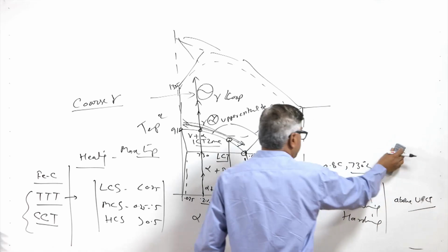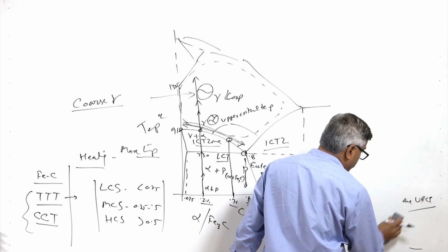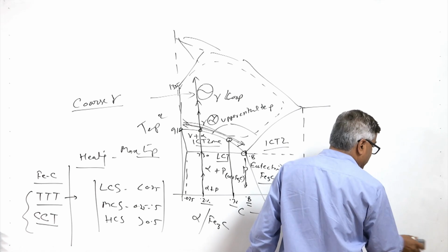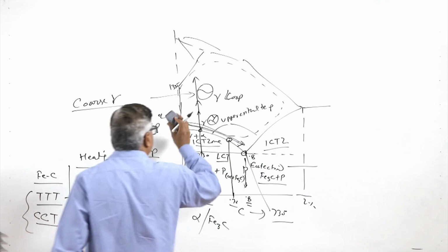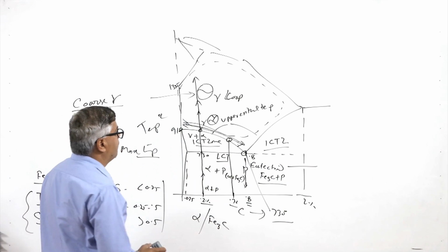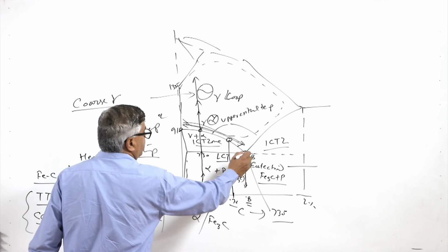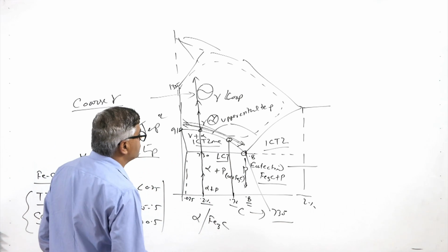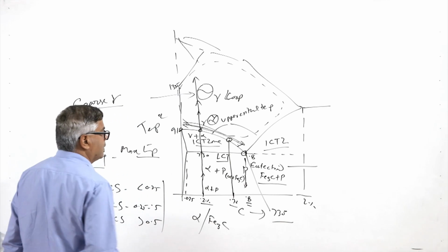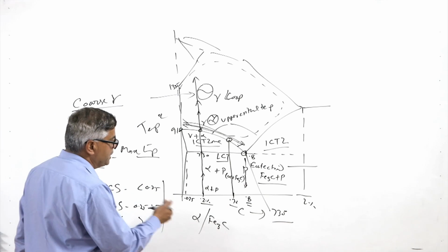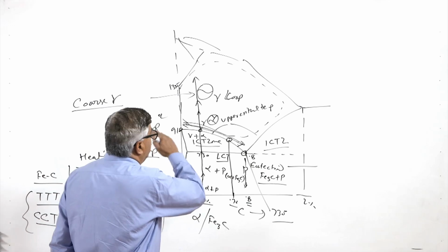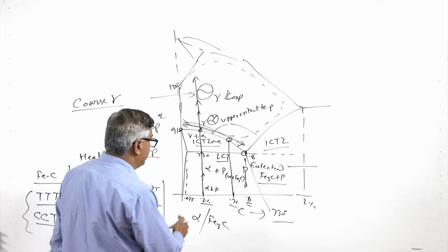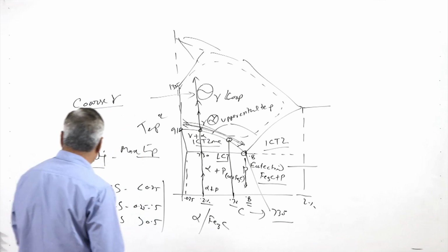As per the composition of the steel being heat treated, the suitable temperature for heating can be identified from the iron carbon diagram, since the upper critical temperature limit and the lower critical temperature values are a function of the composition. So, this iron carbon diagram will help us to see how the upper critical temperature limit for the heat treatment can be identified for a given composition of the steel.